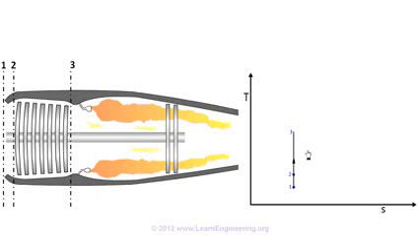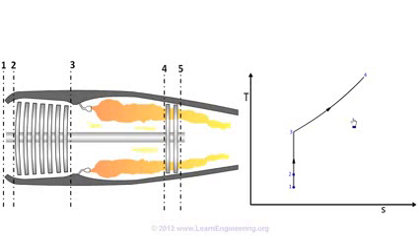This process happens almost at constant pressure, and the temperature of the stream rises to a very high level. Right after that, the turbine will absorb some amount of energy, which is required by the compressor. So here the temperature and pressure of the fluid come down. The last section, which produces the high-velocity jet, is the nozzle. This is again a constant entropy process, where the internal energy of the fluid gets converted into kinetic energy. Here the pressure of the stream expands to the surrounding pressure.